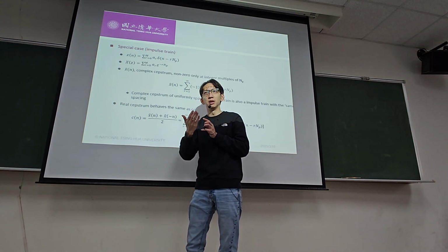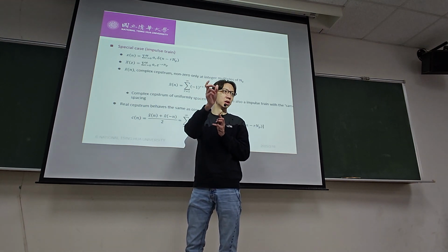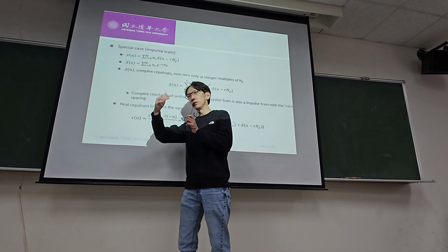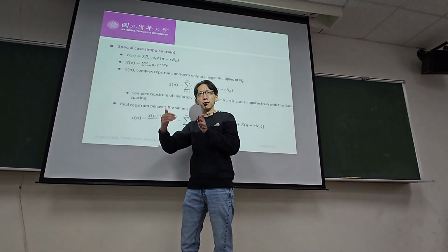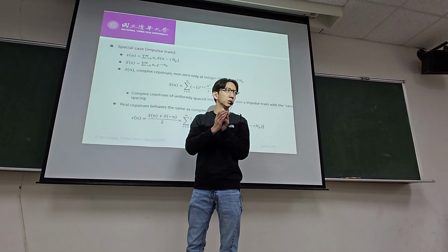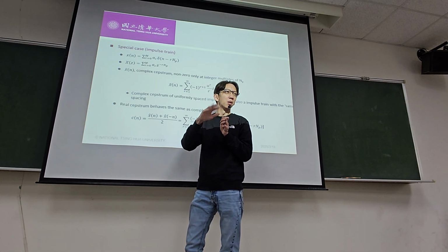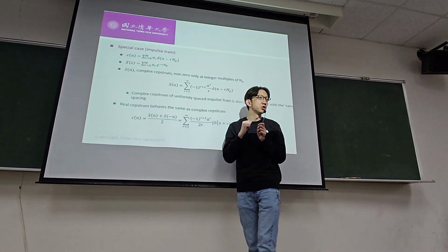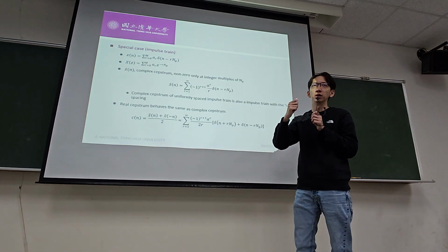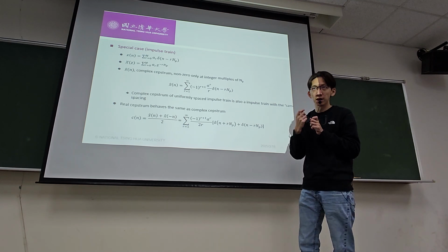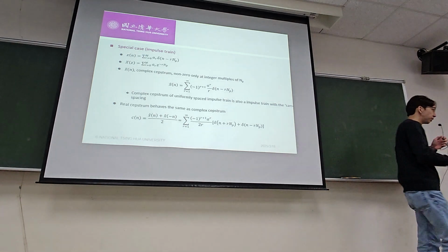The only thing that's different is the log in between, and that log scales the value so that if you originally have two signals that are multiplied, they become additive. That's the whole beauty of math, and we're applying it in the space of speech technology. This whole thing we call cepstral transformation, cepstral domain analysis, cepstral computation, whatever you like to call it.